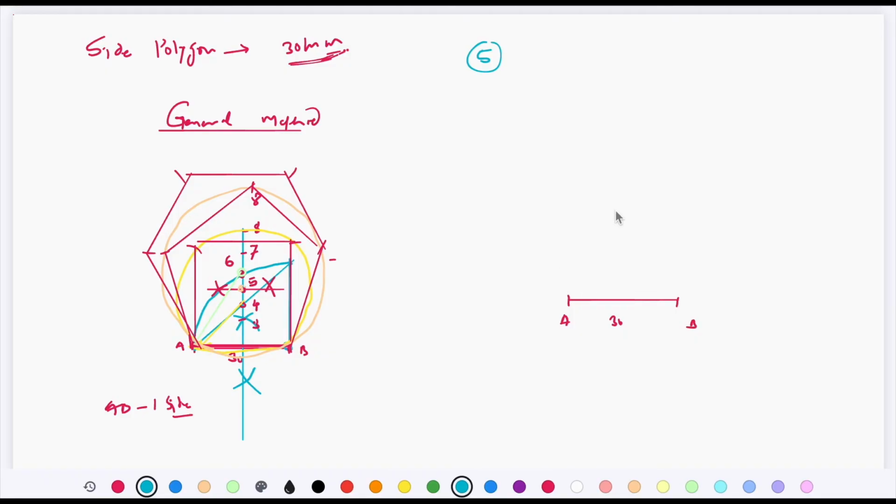As I am going to draw a 5-sided polygon, the total included angle in case of a circle is 360. So I will divide it by 5 because I am drawing a pentagon. So you will get 72 degrees. This 72 degrees is called the external angle.